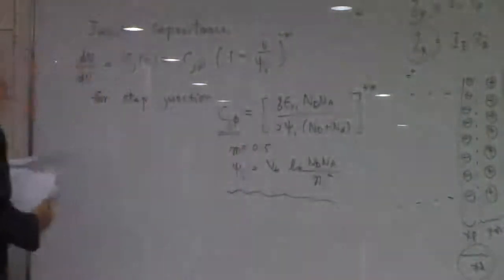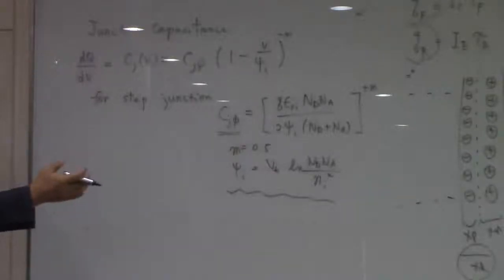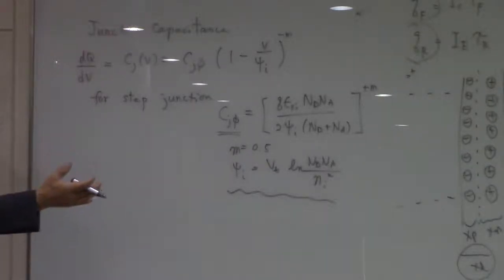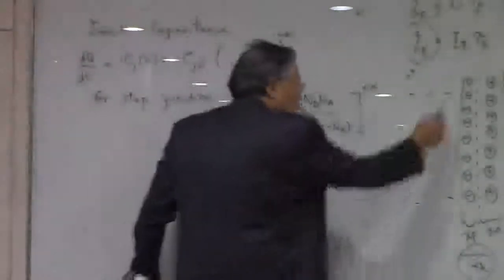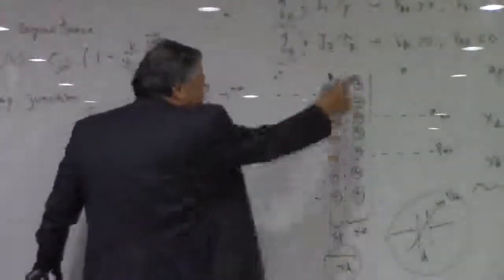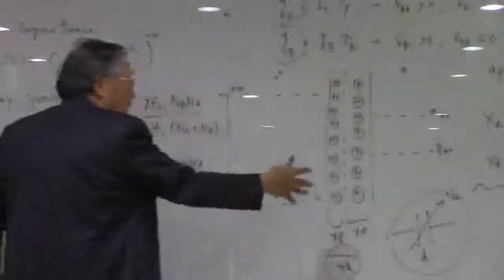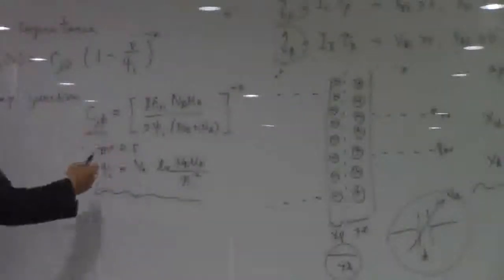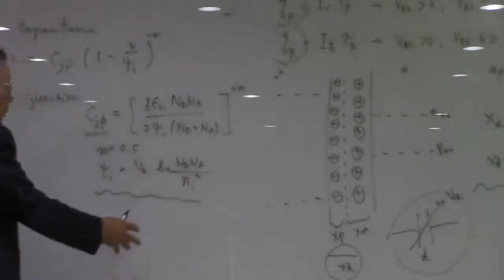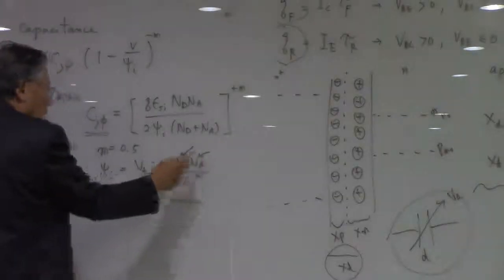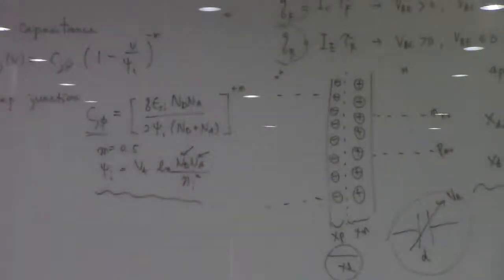Without any voltages, if you make a p-n junction, then we do have a space charge region like this, which can be regarded as a capacitor, and the distance is going to be modulated with the applied voltages from the outside circuit. So without any voltages applied, the junction capacitance can be totally determined by the dopant concentrations here. That is the only variable we have.